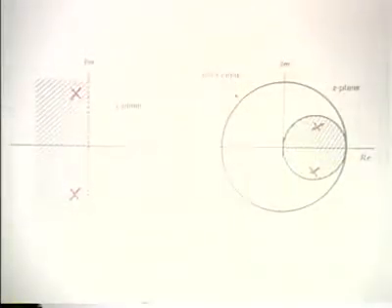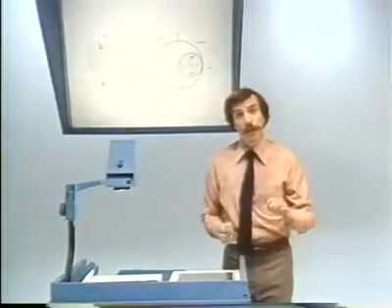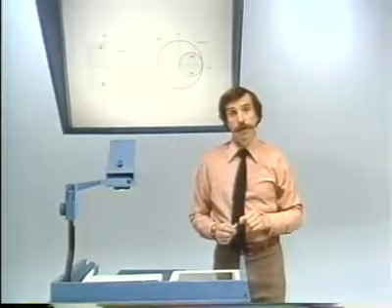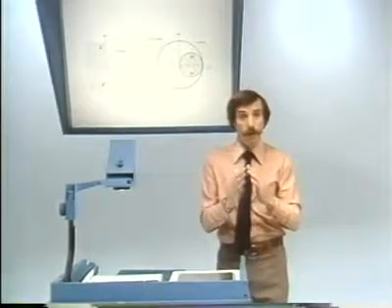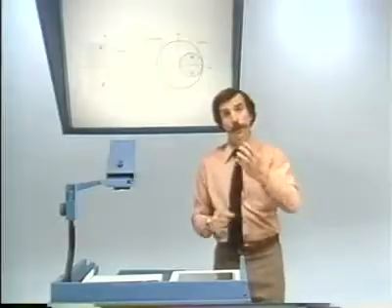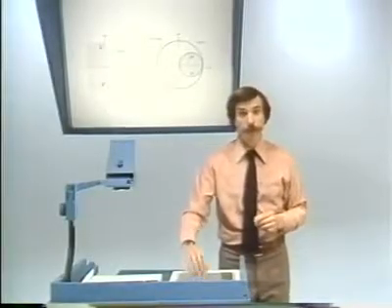So what would happen then is that if we saw in the continuous time filter a very sharp resonance, the discrete time filter might very well have that resonance broaden considerably because the poles are so far away from the unit circle.